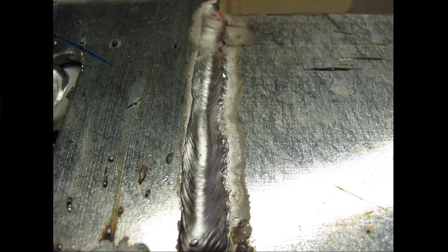Now, one of the telltale signs is this undercut right here. So this nozzle, this is one of those things, this nozzle needs cleaning. This is not a thing you're going to sit here and wrestle with all night in your reprocess station, if in fact that's what you're doing. This is not something you're going to wrestle with. You're going to stop, and we're going to get somebody over, and we're going to get that fixed, because that will only get continually worse.